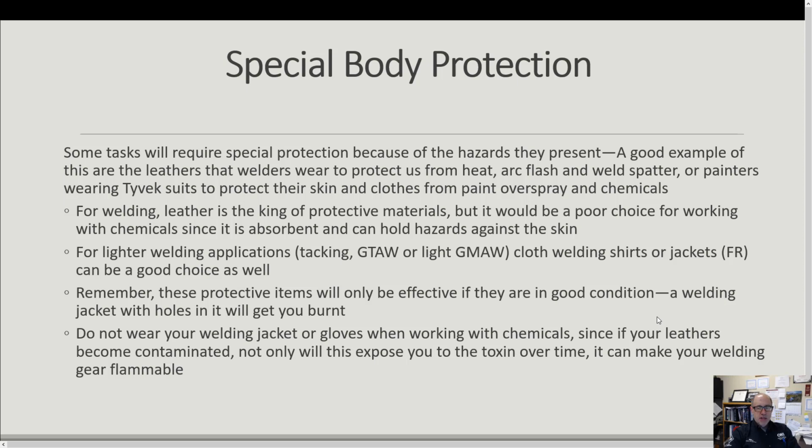And don't wear your welding jacket or gloves when working with chemicals, since if your gloves or leathers become contaminated, this will continuously expose you to that toxin over time, and it can make your welding gear flammable.